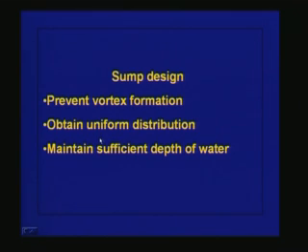Another thing is, if you are having more than one pump, or 3 or 4 pumps which are operating in parallel, then we have to get a uniform flow distribution in the sump. We also have to maintain sufficient depth of water in the sump to prevent air entry.